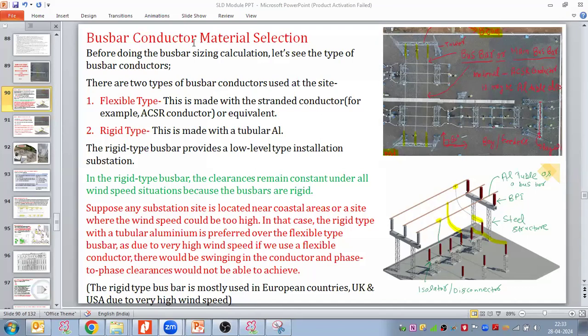If in your case there could be a particular reason due to which they have not indicated it with the line bay, you share me the SLD, and I can speak to you one-to-one. But ideally, it should be placed with every line bay, so that we can get at least the synchro check.